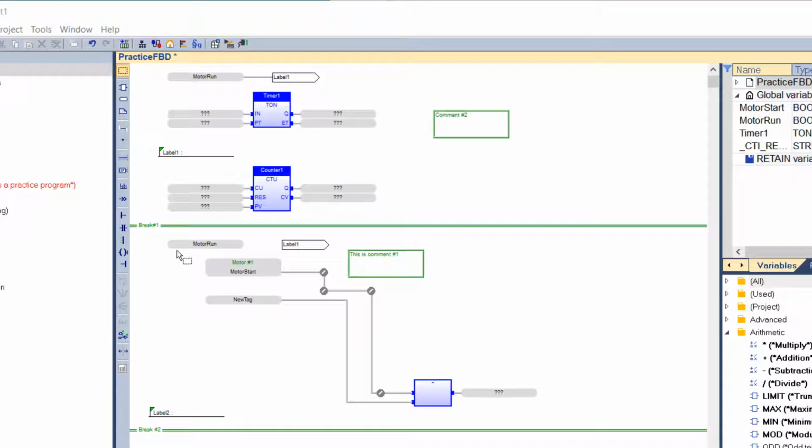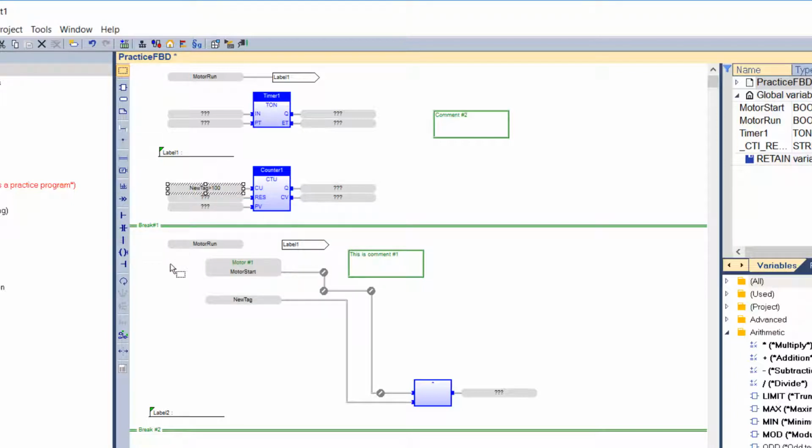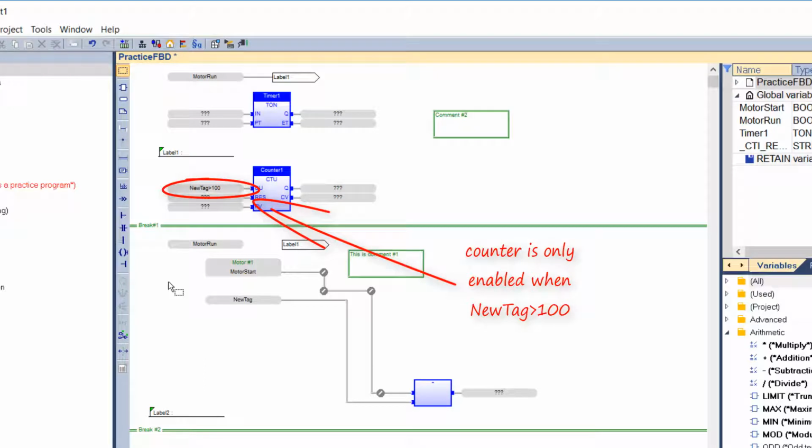Complex structured text expressions can be used with any graphic element in FBD language, making it possible to simplify the diagram when a calculation needs to be entered. The expression must be written in ST language, and must fit the data type required by the diagram. For example, an expression put on a contact must be Boolean.